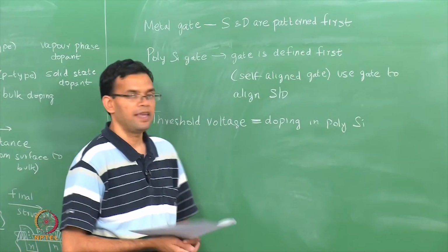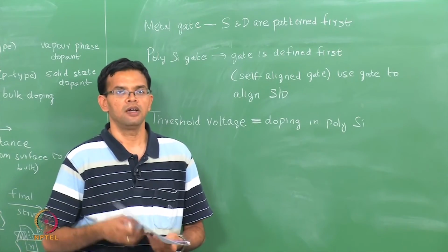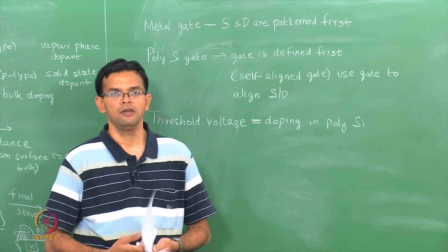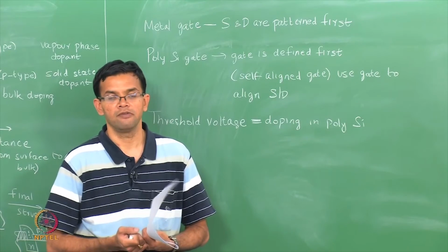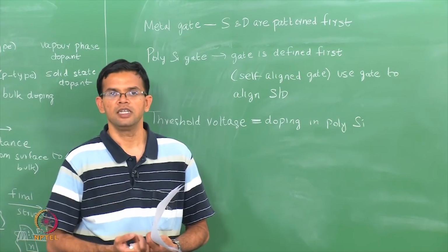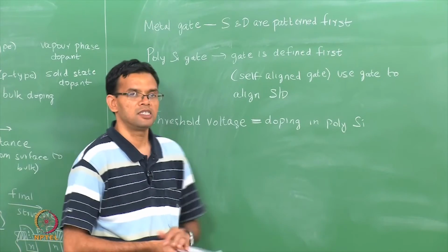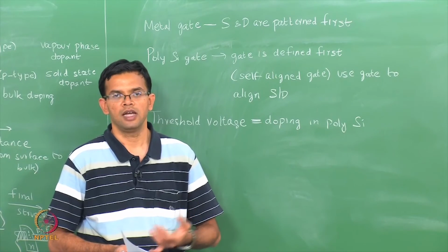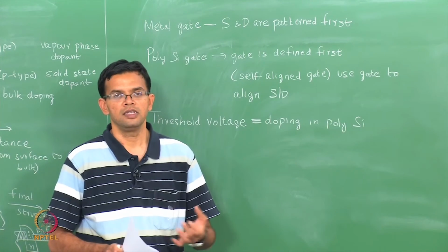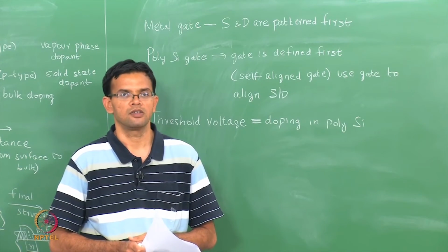Once again, your gate oxide material could be a thermally grown silicon dioxide, or you can also replace it with other materials like oxynitrides or high K dielectrics. MOSFETs essentially form the basic building block of your IC circuit, and these form the logic component of the IC circuit.